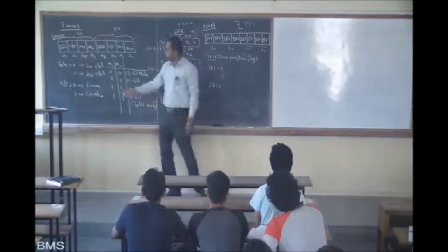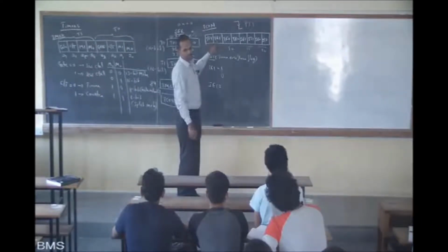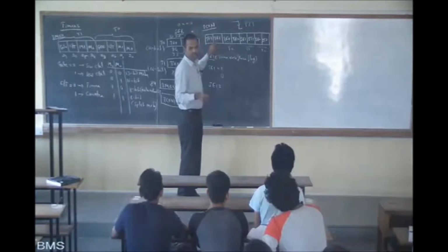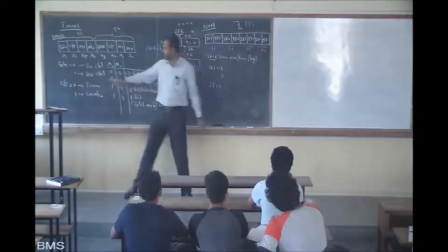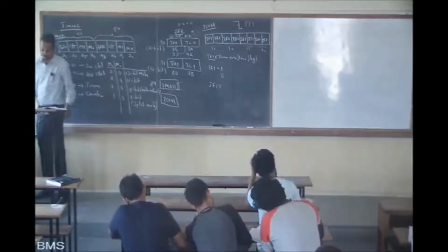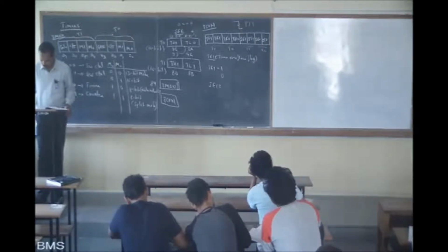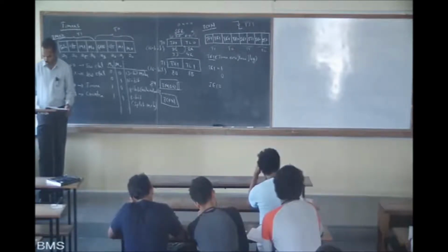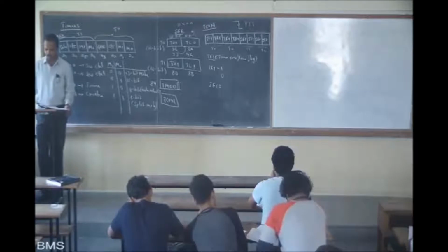And this works only when gate is 1. Hardware control. What do I mean by software control? Making the TR bit 1. TR1 is software controlled. Here you are setting it by the pulse on this pin, so it is hardware controlled. That is possible, yes, if gate is 1. Is it clear? Below that, write: this works only when the gate equals 1.